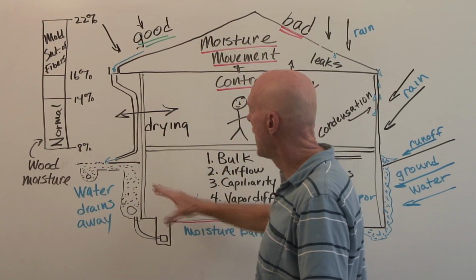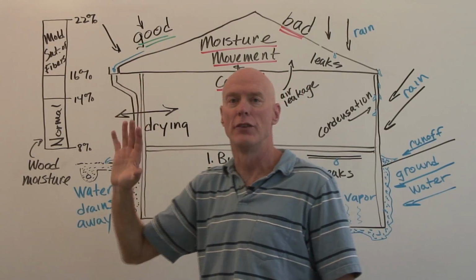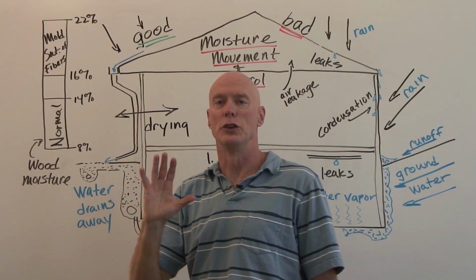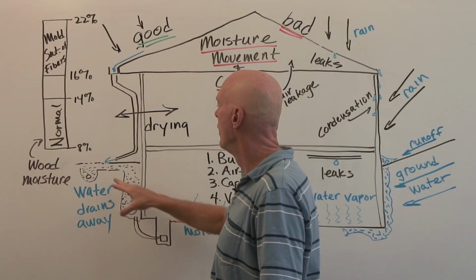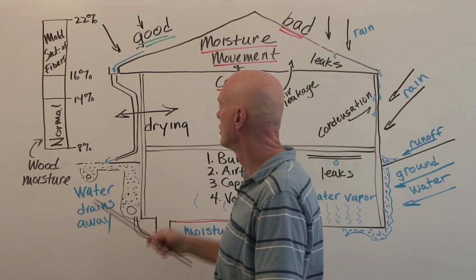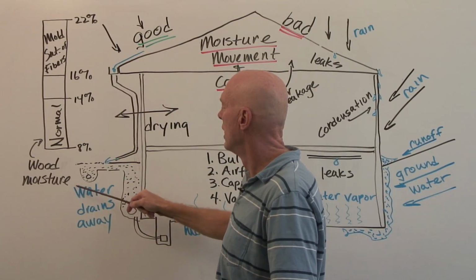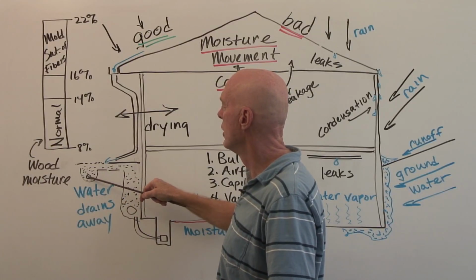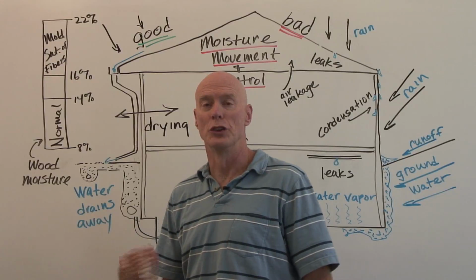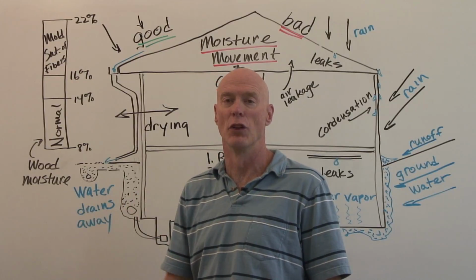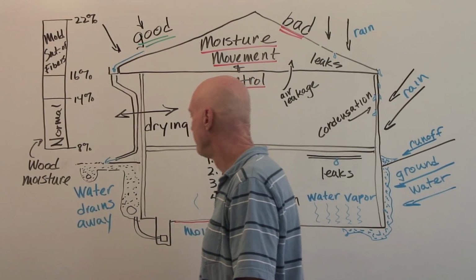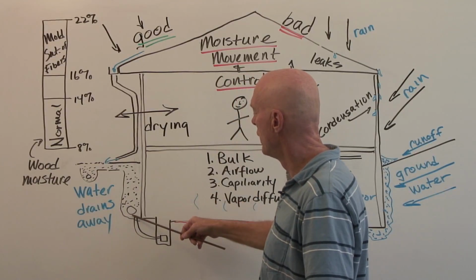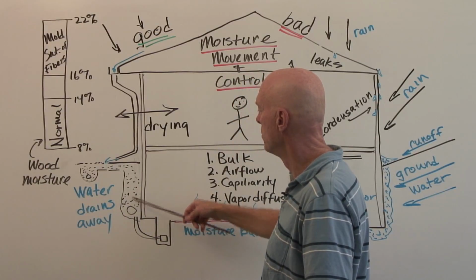And if we have serious problems with a lot of rain, if you live in a rainy climate, then we may have to create some kind of a sump here which will help the water to drain away, either by use of a drain pipe or just by the natural percolation of the water into the ground. Here against the foundation, again, we may have some drain pipe.